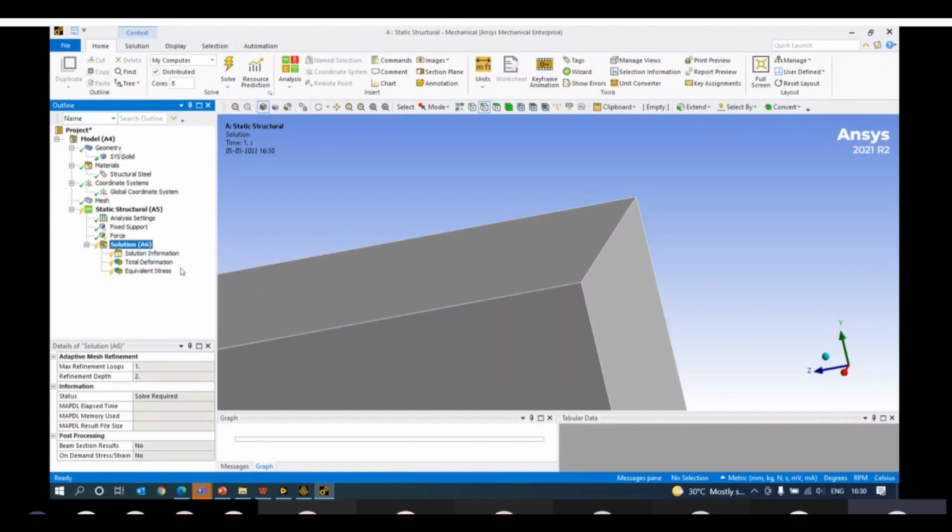So this process enables you to know from the tree what all different things you are going to work on. So mesh, defining boundary conditions, getting the solution. But when you move on to more than a single component, you also have to work on your connection part.